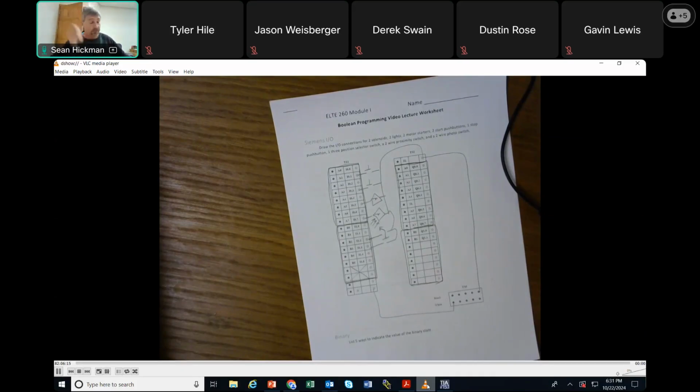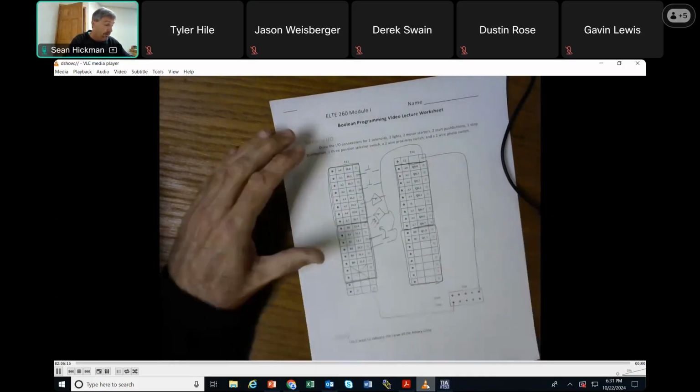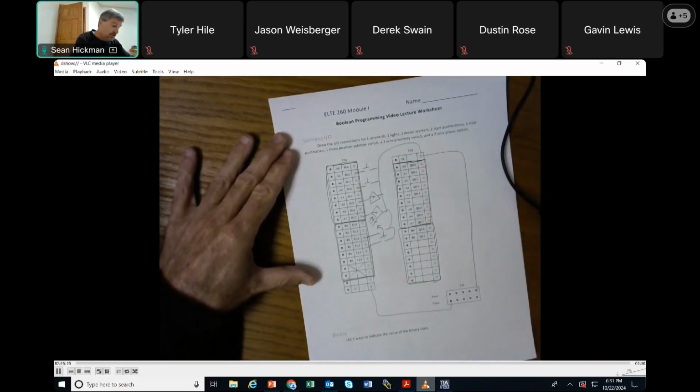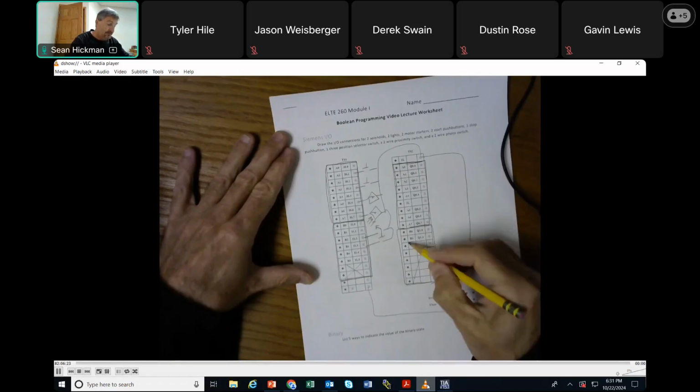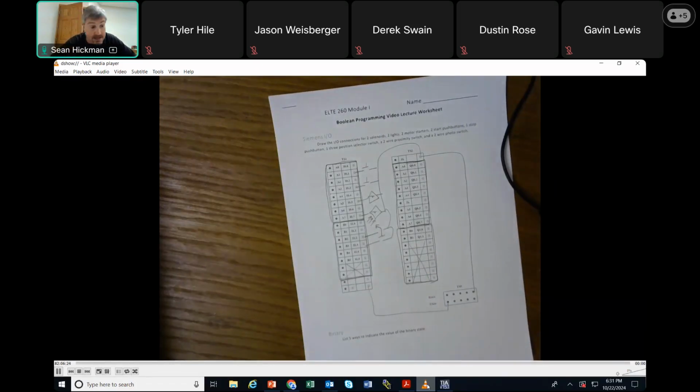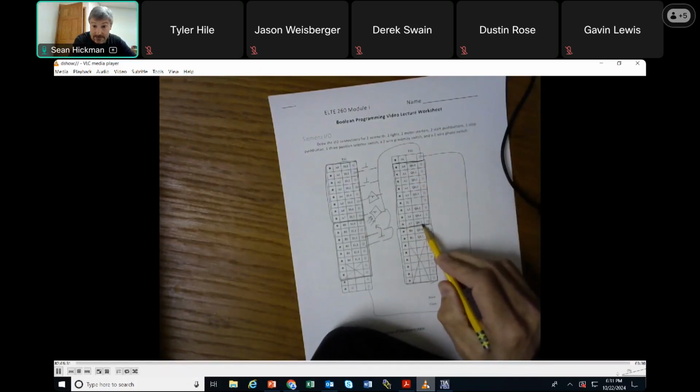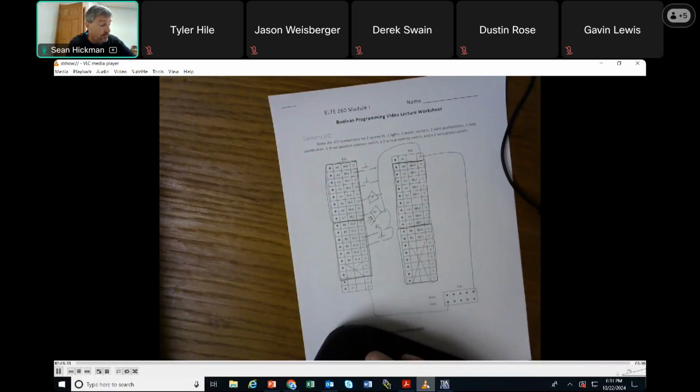Good. All right. So now we're going once again to my outputs. And remember, they're grouped by 8, but we only have 10. So the rest of this byte is not available to us for addressing. But it does go from Q0 up to Q.7. But now what gets a little more confusing is the sourcing of them. The sourcing is by groups of 5.